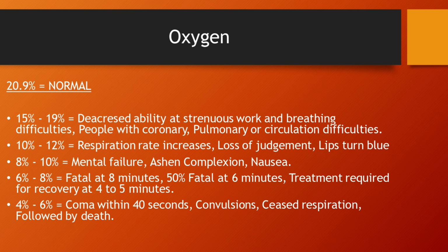Oxygen, 20.9% equals normal. 15% to 19% equals decreased stability at strenuous work and breathing difficulties for people with coronary, pulmonary, or circulation difficulties. 10% to 12% equals respiration rate increases, loss of judgment, lips turn blue. 8% to 10% equals mental failure, ashen complexion, nausea.